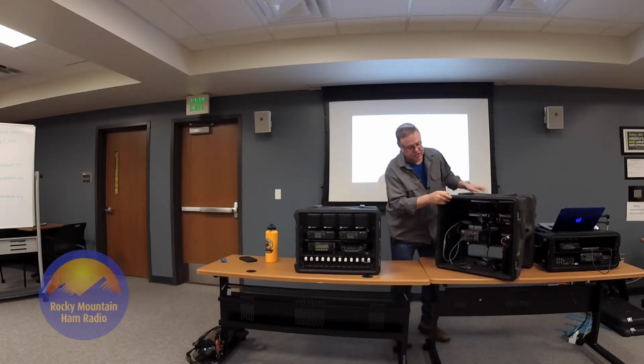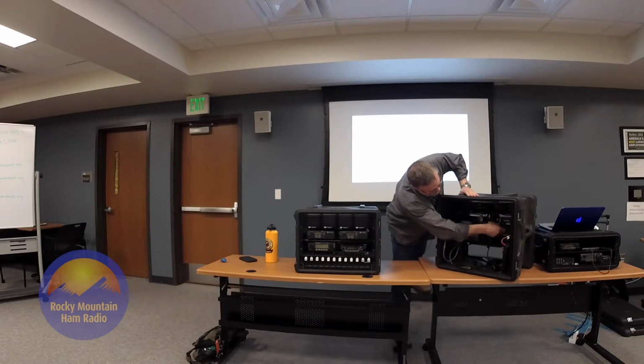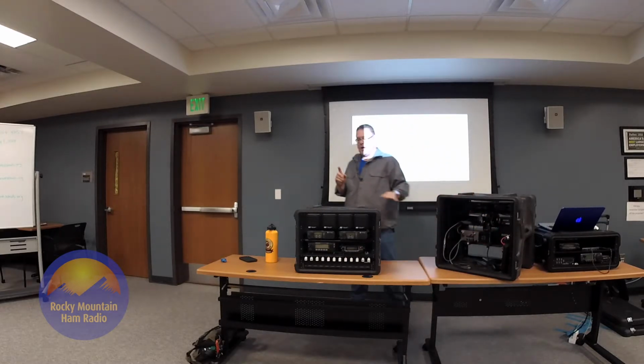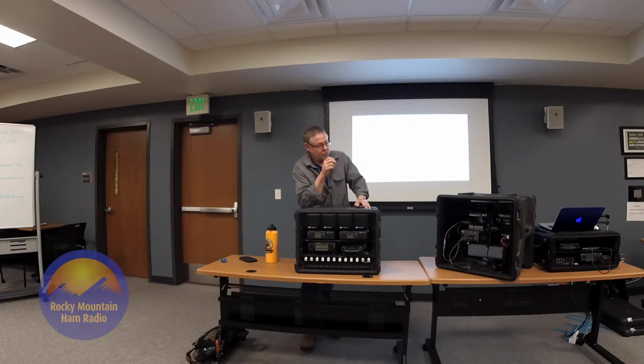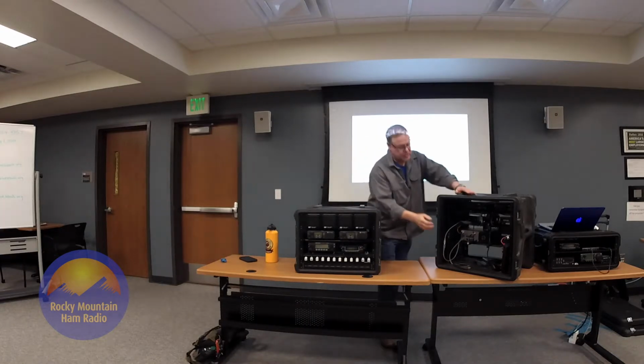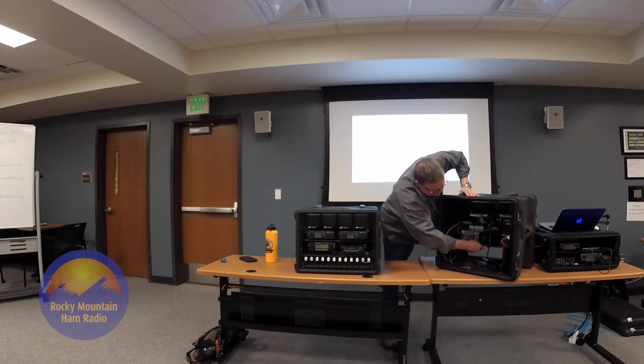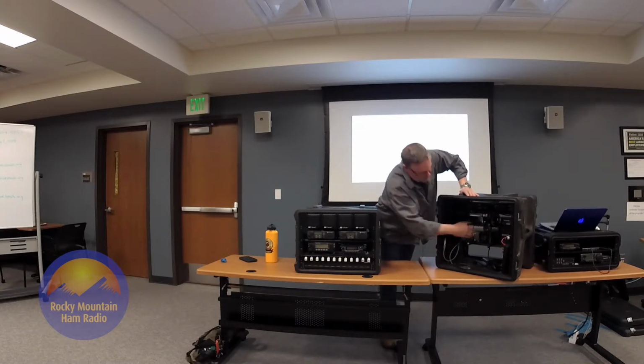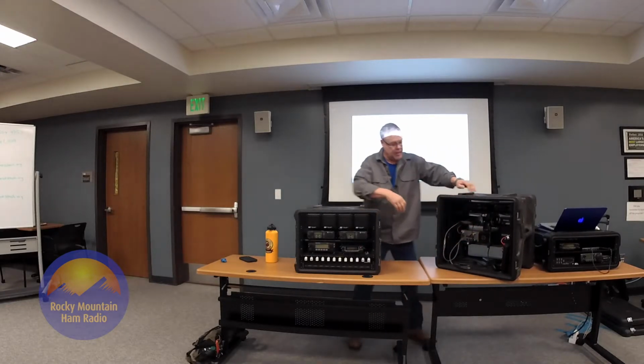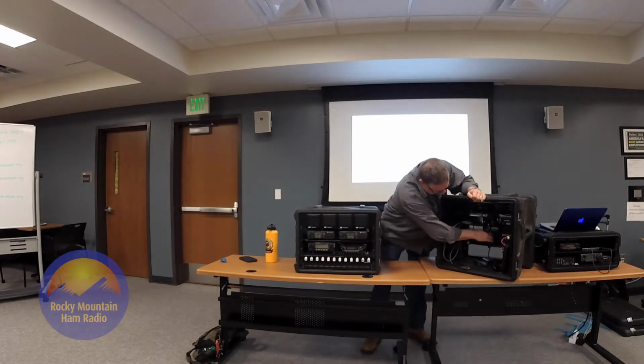Another reason the slotted shelves are good, wire ties. Everything's managed here. Power management is your biggest concern when designing these things. Your second concern is the management and the durability and the mounting methods you use for mounting your equipment. These shelves, as you can see, give a little bit, but not much. Mount your equipment, hard mount it.